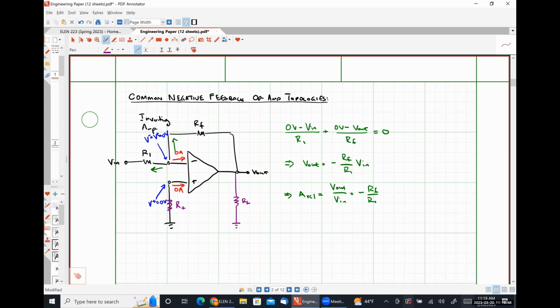It's to eliminate a phenomenon called input offset currents. Effectively, they're very, very small currents that can flow and will cause your output voltage to drift slightly. And so you just use a resistor there to correct it. For our analysis, it does nothing, but in a practical sense, it does have a use. Much like a load resistor, that's something we're trying to drive using this amplifier circuit, but from the analysis perspective, it really doesn't do anything, so we very often don't include it.